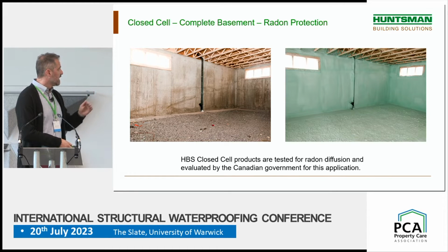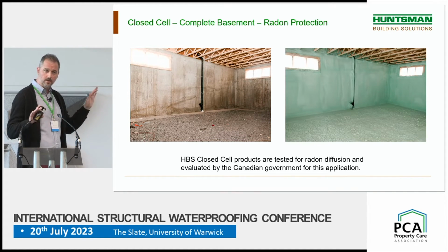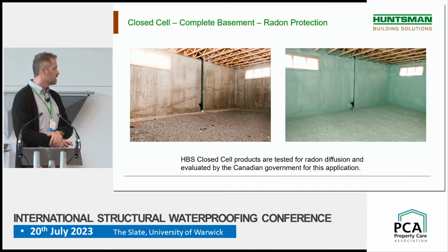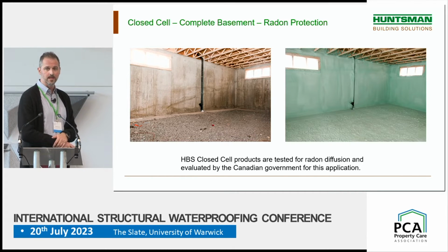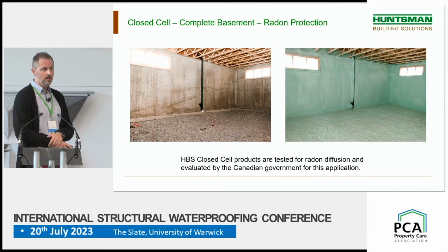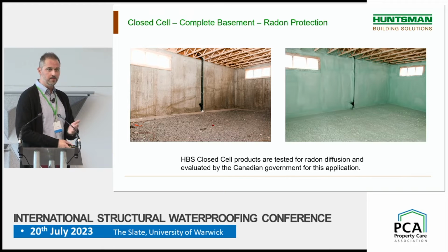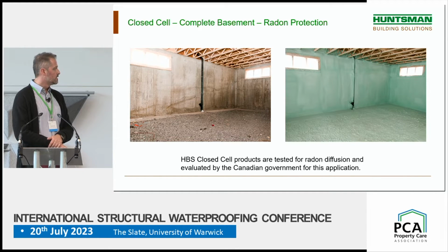So just a before and after picture, so you can see that the basement is completely sealed. As I was saying, no joints at all. So really preventing radon gas from entering the building, as well as insulating. The Canadian government also evaluated this application for radon prevention and provided the CCMC evaluation, which is similar to the BBA or Kiwa evaluation here. It confirmed that the product was a radon barrier, an air barrier, and also puncture resistant. And we'll see this in a second.